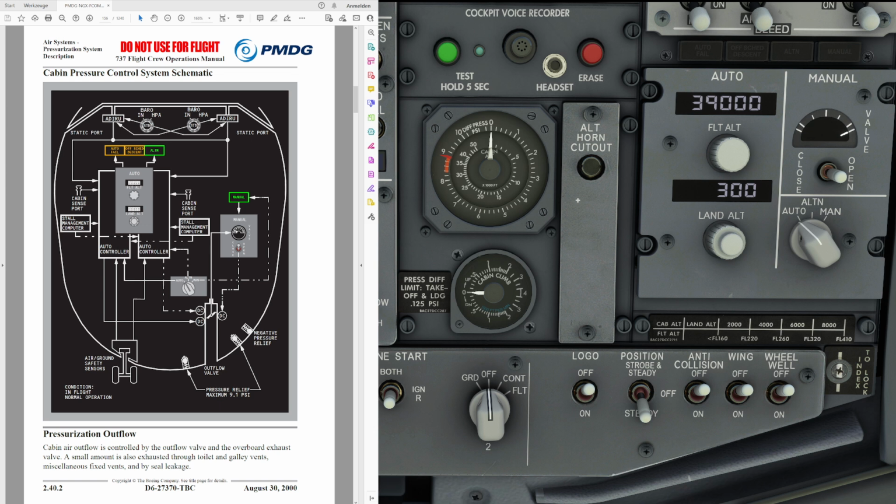The overall system works like this. When the airplane is at the maximum certified ceiling of 41,000 feet, the cabin altitude is around about 8,000 feet. We can see the cabin altitude versus flight altitude table up here below the cabin controller. And while we're talking about the layout of the panel design itself, there are two different panels available. Both, however, work the same way, so I'm not going to go into showing you the other panel in this very video. I have made a video, however, introducing the new pressurization panel that we currently see in the flight deck in here already.